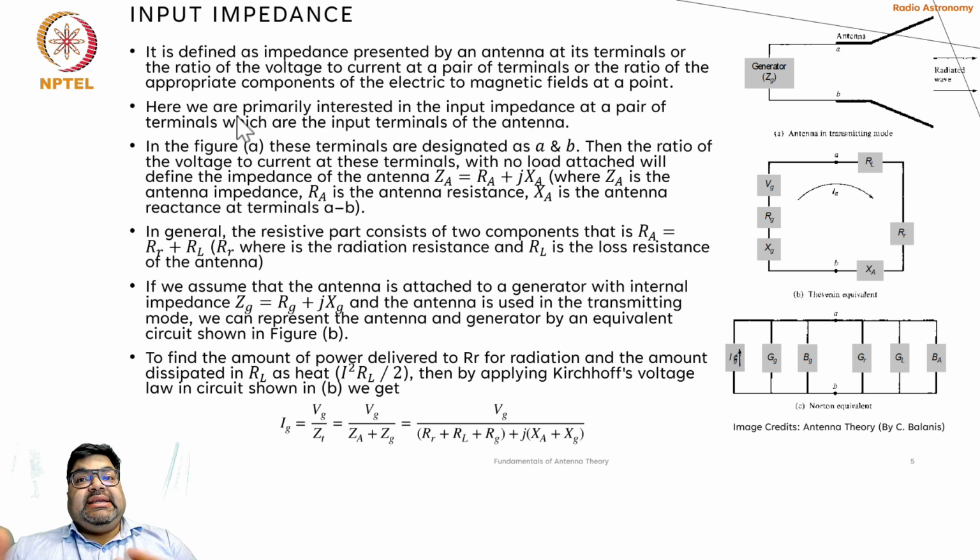An antenna itself, by its characteristics, also has a polarization property. Now, this too has to be disentangled to understand the inherent polarization property of the radiation coming from the cosmos itself. We will talk about it a little bit when we come to it, but please note it down that this has to be done when you actually analyze. Otherwise, you will get a wrong answer, or the measurement of the polarization of the source which you are observing in the far field sky will become erroneous.